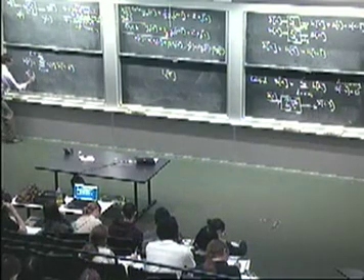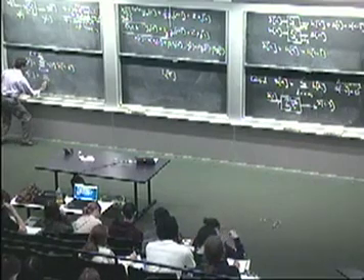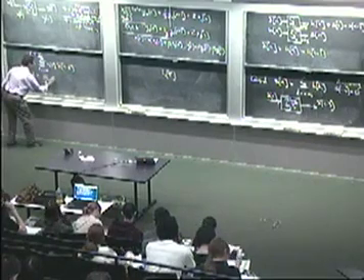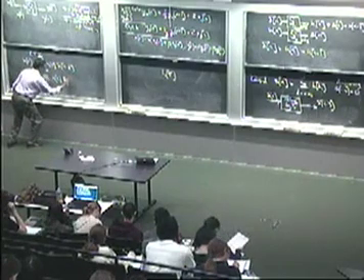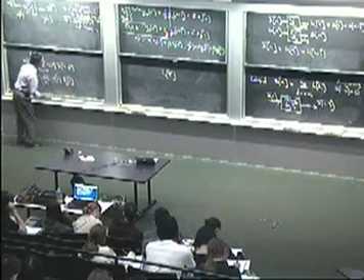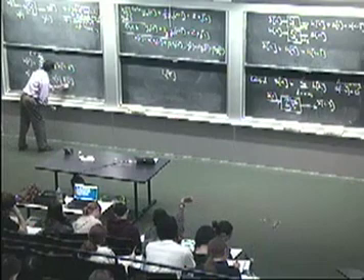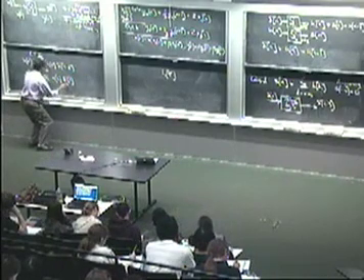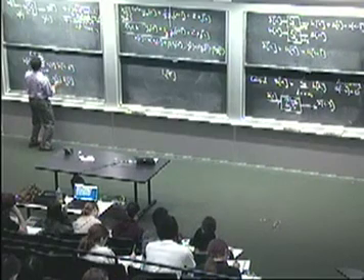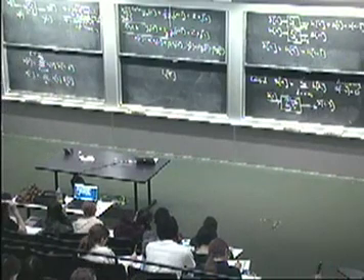Another way to say this is, here's a time function going in. It's a weighted combination over all possible values of k, of x[k] times, and this is my other notation, remember, for unit sample functions. Sorry, this should be delta sub k. Yeah, okay. So this is another way to write the same thing.